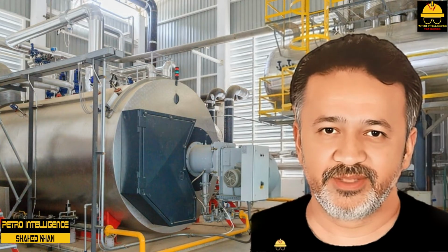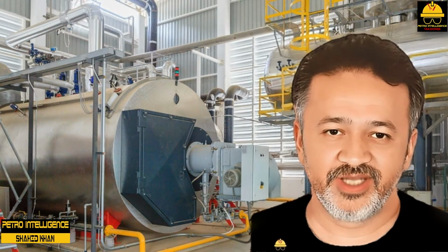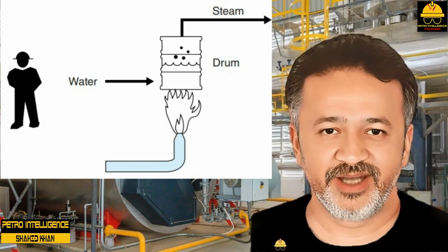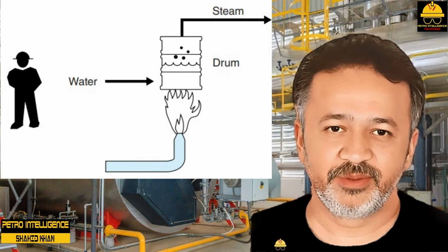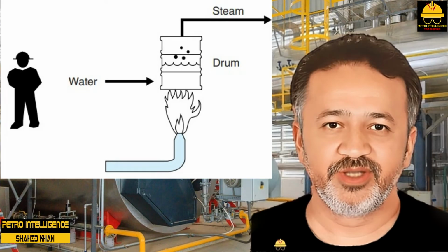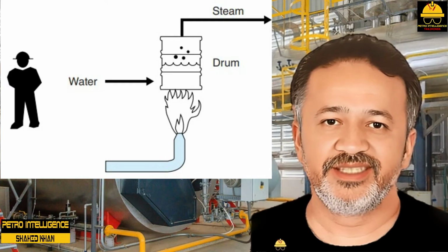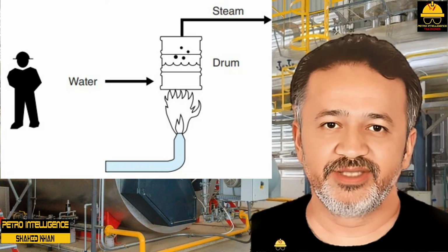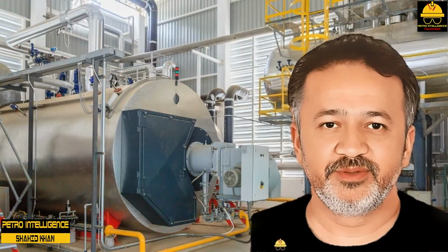heating to process equipment. Boilers use a combination of radiant, conductive, and convective heat transfer methods to change water to steam. A simple boiler consists of a heat source, water-containing drum, water inlet, and steam outlet, as shown in the picture. As heat is added to the drum, the temperature increases until the water boils. As the steam rises, it is captured in a line and sent on for further processing. Factors that affect boiler operation are density differences for internal circulation, pressure, temperature, and water level.